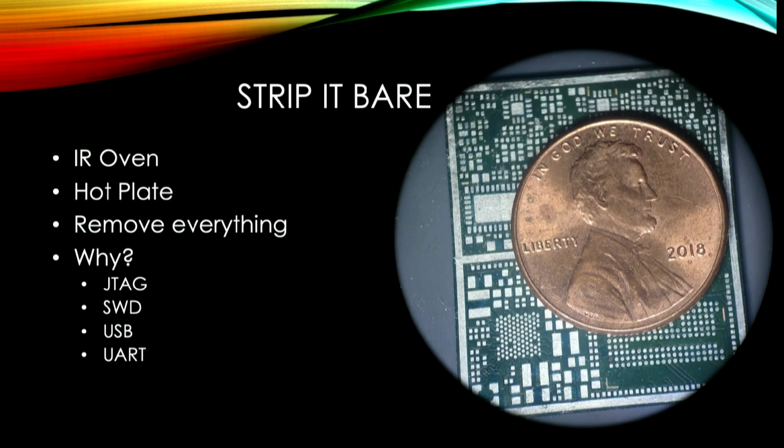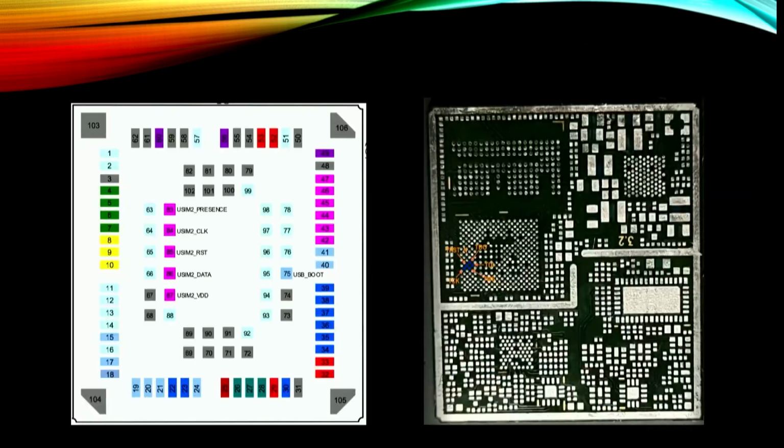And then those are attached to the board within the IoT technology. The connections on the underside, instead of being a ball grid array, are known as LGA, land grid arrays. They're larger square pads typically. If a vendor puts the device in their box, there are certain things I may want to look at, and they're not always easily accessible. So I always want to ask, can I attack these from the surface and dig into them?